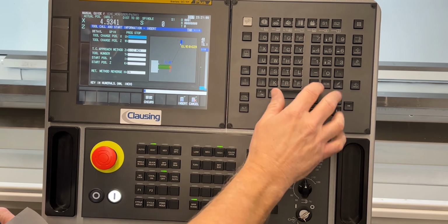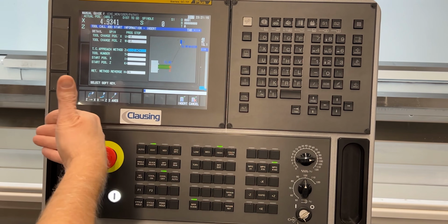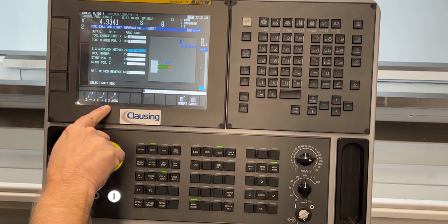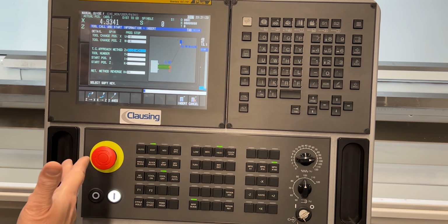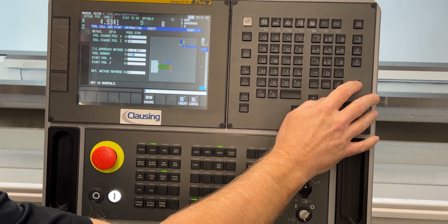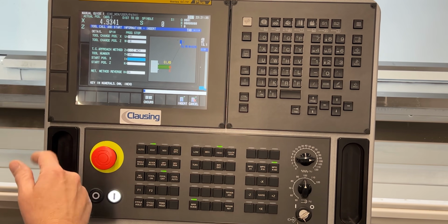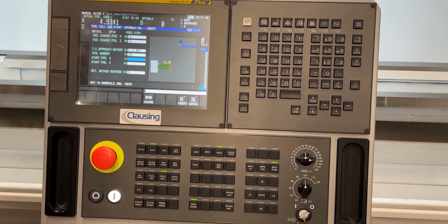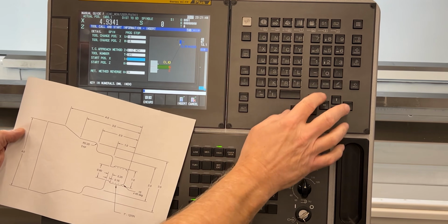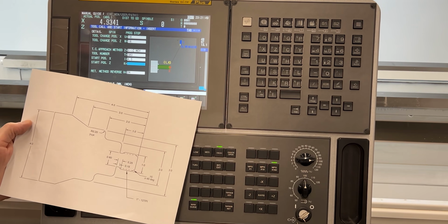This is my tool change position, back away from the part. Let's go 10 and then 10. The TC approach is how we get back to that tool change position. We'll do X first, then Z. We have selections of how we want to do that, depending on what you have to move around. We'll call up the tool number, which is going to be 3, so T303. Tool 3, offset 3. Then the X start position is approaching back to the part. The part is 4-inch diameter, so we're going to leave it somewhere out there, clear of it. Let's do 4.5 and Z of 1.